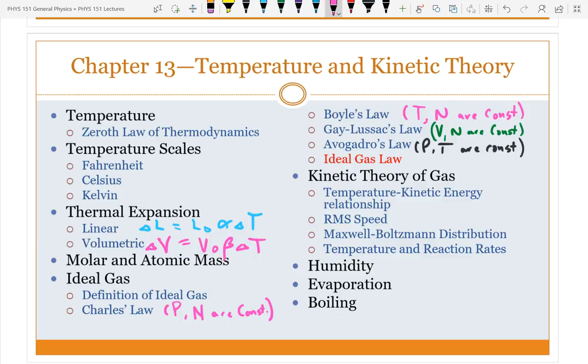What's the condensation temperature for water? 100 degrees Celsius. Below 100 degrees Celsius, it's going to be liquid water. Above 100 degrees Celsius, it's going to be steam. For water vapor, steam, to behave as an ideal gas, it's going to have to be well above 100 degrees Celsius. So if you have water vapor at 150 degrees Celsius, you can't treat it like an ideal gas. But on the other hand, if you have water vapor at 500 degrees Celsius, yeah, knock yourself out. That's well away from the condensation temperature.